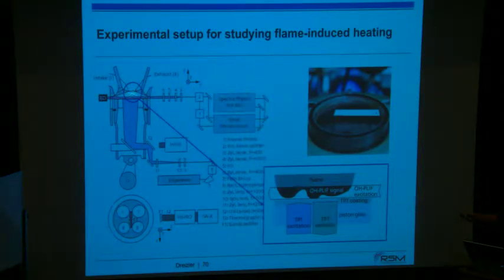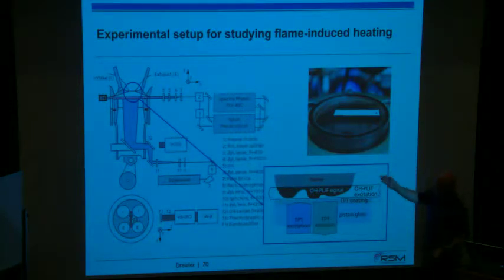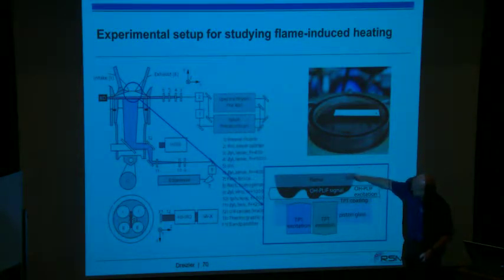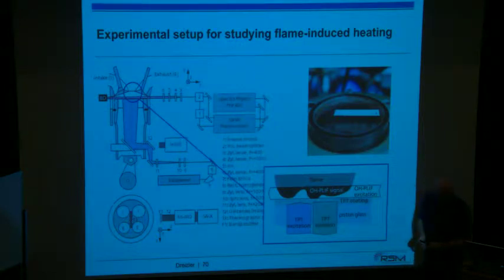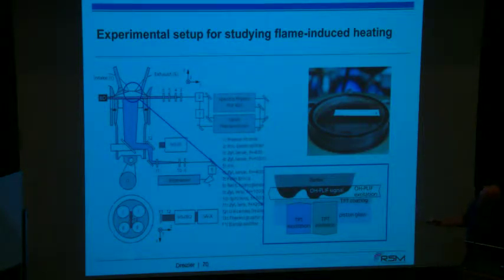And this is shown schematically over here. After ignition with the spark plug, a turbulent flame propagates, and eventually it comes close to the piston surface, as shown here. And then the last few millimeters have been observed by exciting OH and monitoring the OH with this high-speed IRO in combination with the CMOS camera, looking at this very small light sheet.